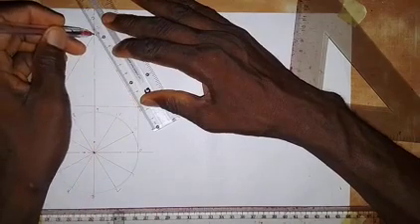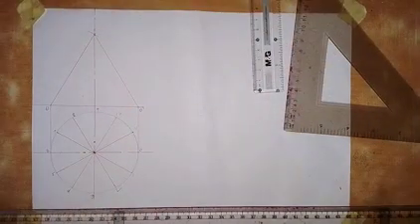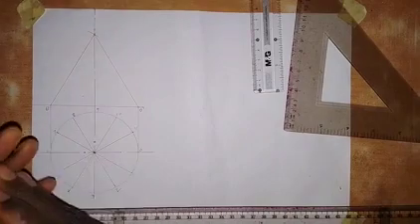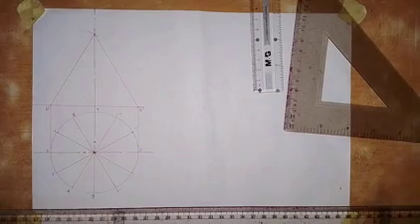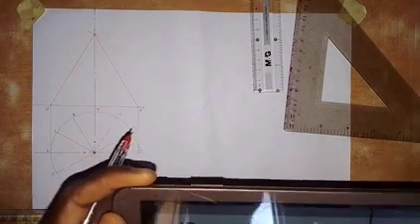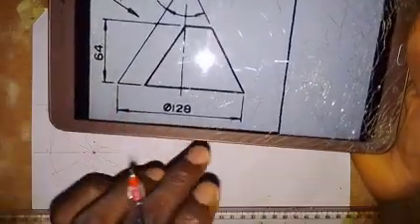So that gives us an equilateral triangle. So this is an equilateral triangle. From this equilateral triangle, we are going to bring out the truncated cone. So looking at the shape, look at what we are given here. This thick line on the cone is parallel to this line, and it starts from this center line here on this chop face. So by the time we draw from here, it will touch this base here.